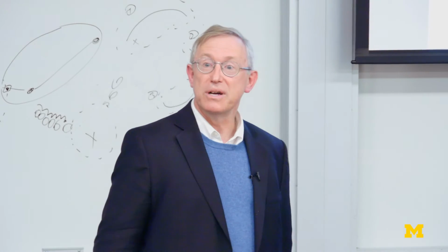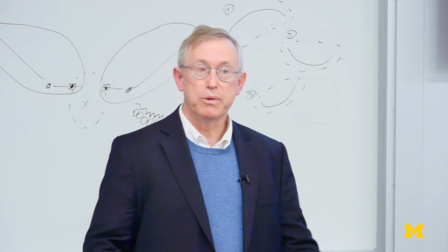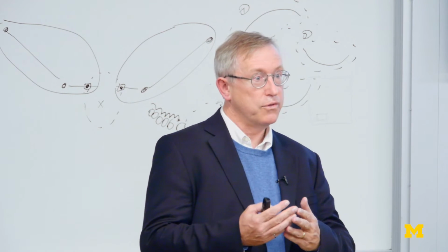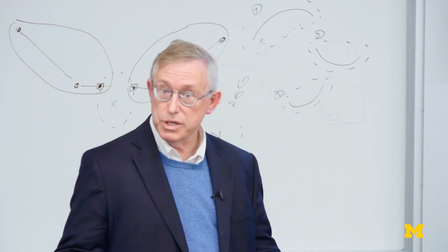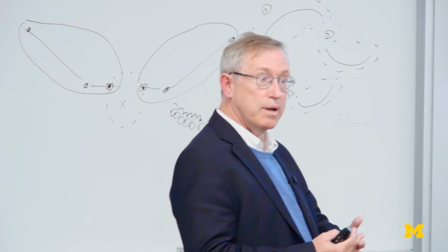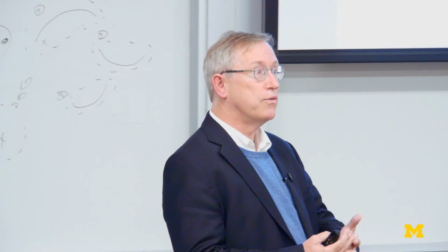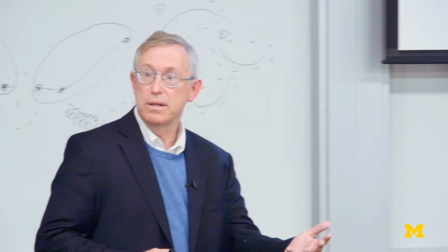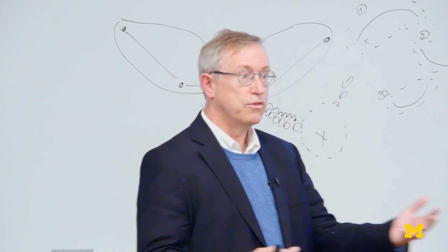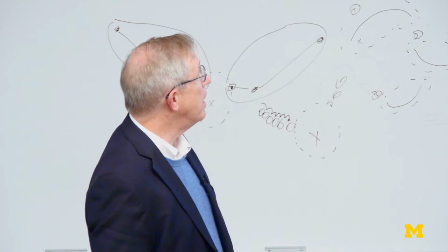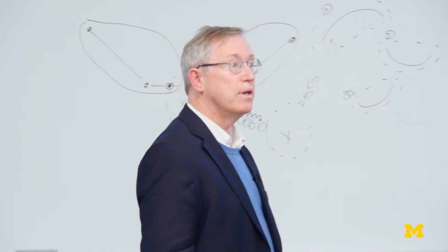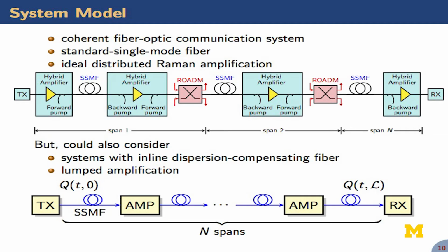There's a whole bunch of different interactions between the signal and itself, so signal-signal interactions, within the channel or across channels. And of course, noise comes into play because we have amplifiers. These amplifiers are going to create noise, and so there are signal-noise interactions. And in fact, noise interacts with itself too, so there will be noise-noise interactions. It gets to be quite a complicated mess.